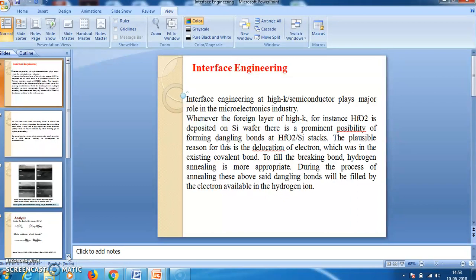This accumulation region may be stable because of a good, thermally stable interface between hafnium oxide, the metal and the semiconductor. Because the hafnium oxide we deposit is stable, it cannot go away easily like germanium oxide, so we have a good accumulation region.